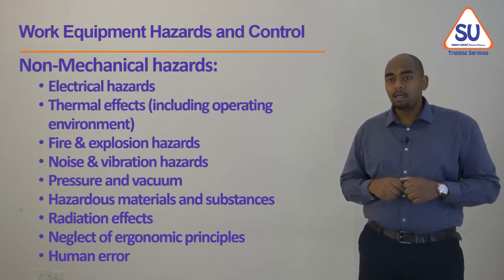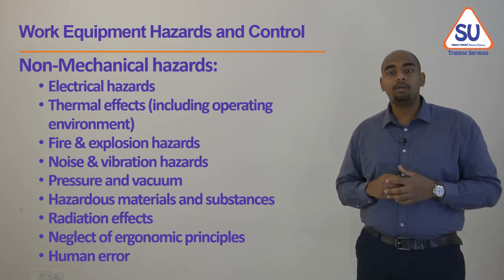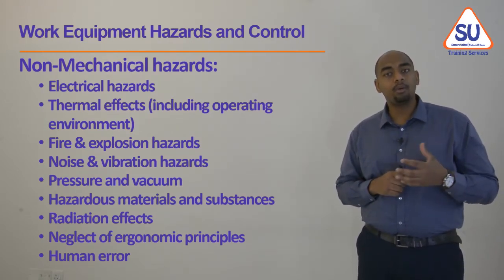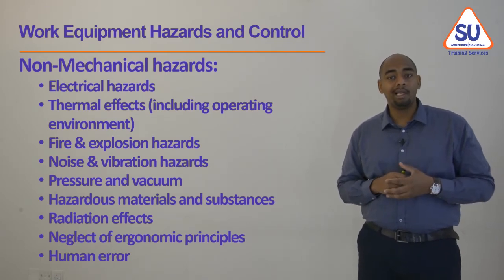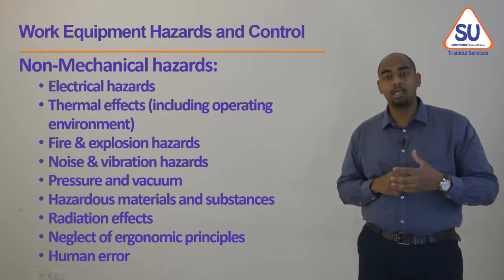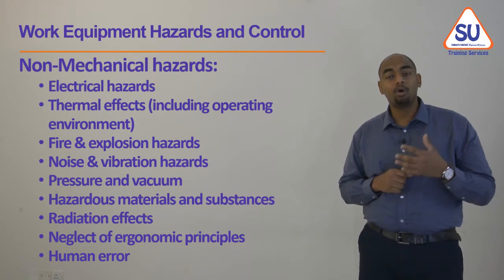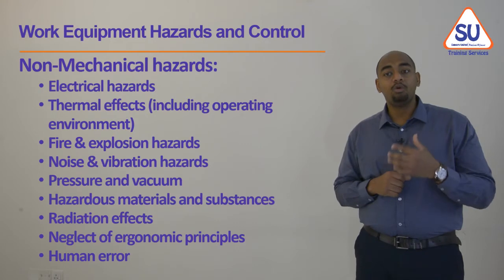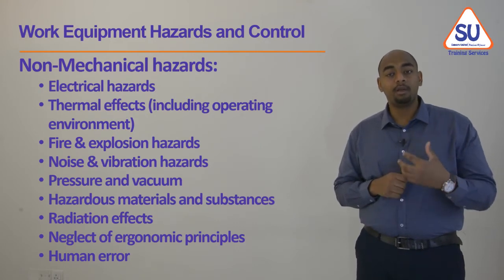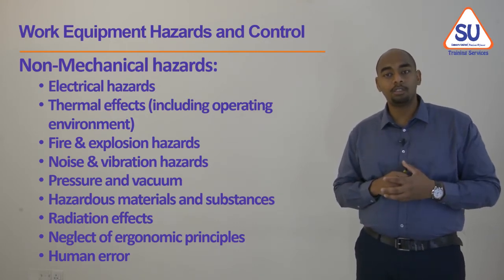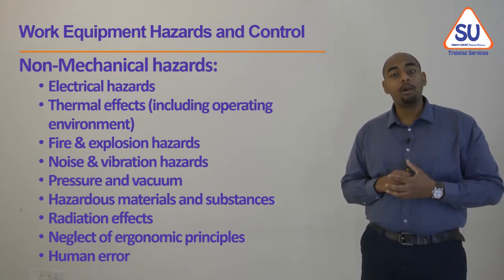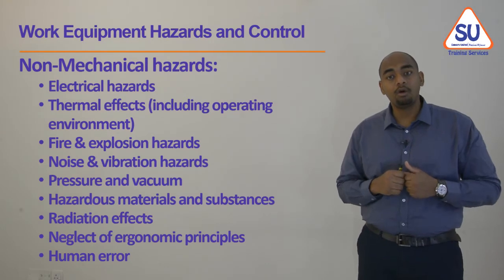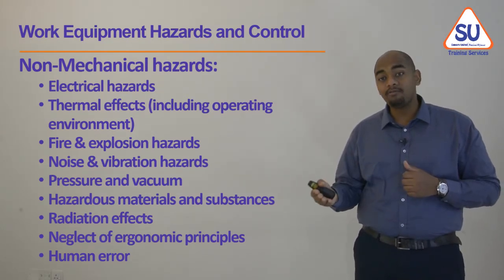Under the non-mechanical hazards, we can include the rest of the hazards related to portable power tools, including electrical hazards that can cause electrical shock to the user or any trespassers, and thermal effects, including the operating environment and overheating of the equipment. Also fire and explosion hazards from the fuels being used, and noise and vibration.